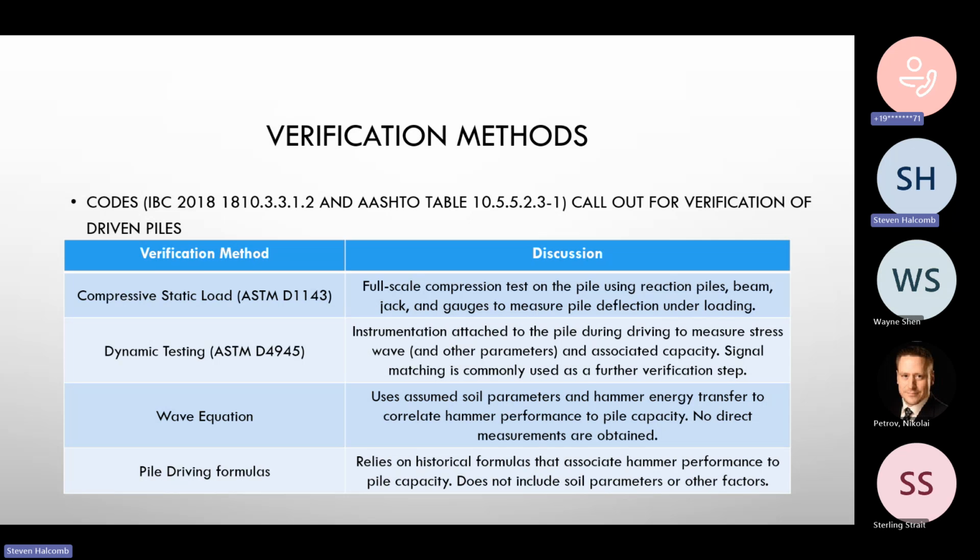So we could talk about what is the definition of a capacity, because you get this kind of modulus curve as it settles as you load it. When we talk about the capacity of the pile, it's almost an arbitrary number you just assign to a curve. There's several different ways to do that, the Davisson method, and other things that define what a capacity is. But it's important to know that capacity is more a concept than an actual number.